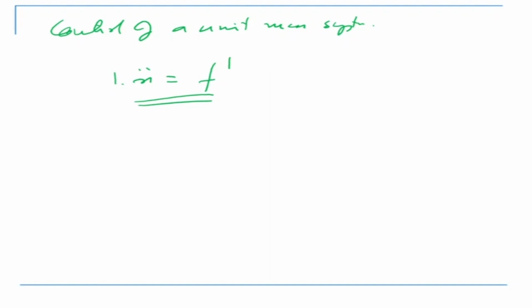This kind of control system is called a partitioned control system, which is very useful for robotics applications. In the next class, we'll see that this kind of control system can also take care of nonlinear systems. This is required because the model part can have errors. There can be variations in the estimation of mass, and in the computation of Coriolis and centrifugal forces. So the concept of the partitioned control system will continue in the next class.